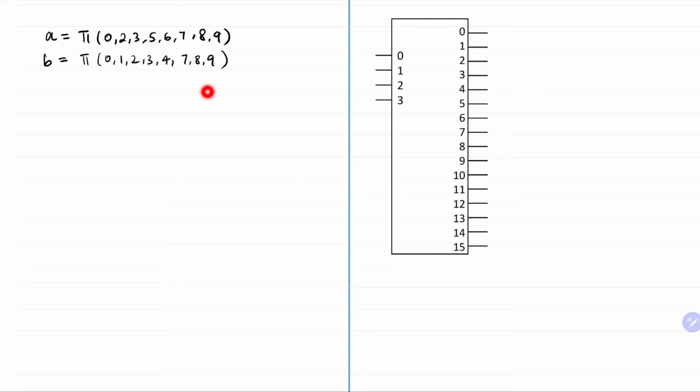So you can see that here, our A and B terms, there's a lot of min terms here. So if you're going to OR all of them together, you're going to use a lot of logic gates. So maybe it's still a good idea to implement it using the max term, or we can look at how we can simplify this.